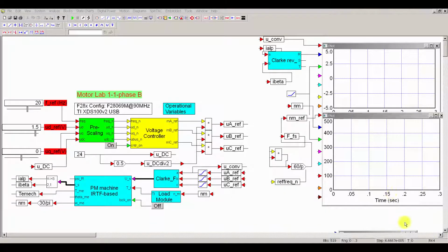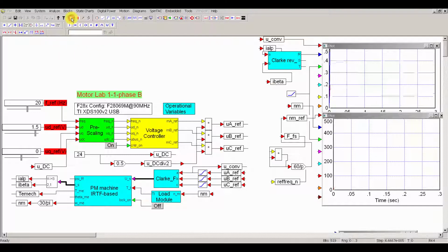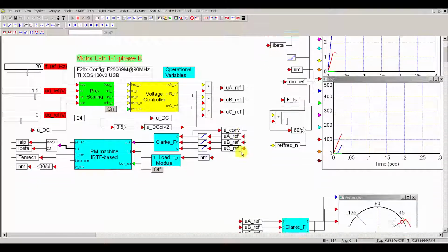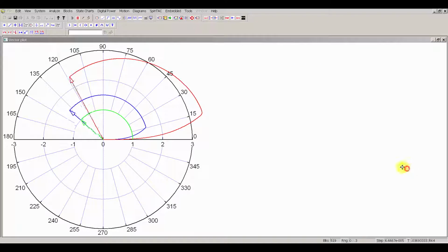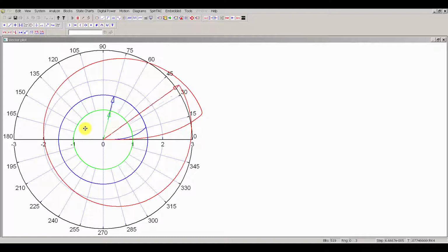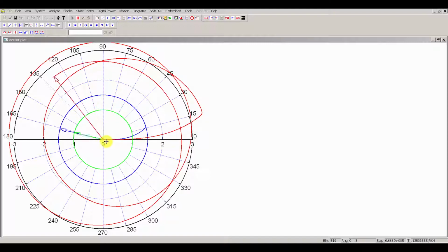So now we've actually run this particular model in simulation. If we run it, we can see here, particularly in the XY plot, which is spectacular, a voltage vector rotating. The switching aspect is not there; it doesn't matter. This is the voltage in blue, and that's the d-axis, so it's a rotating reference frame. What you really want to see now is that we get the same thing done in real machines.